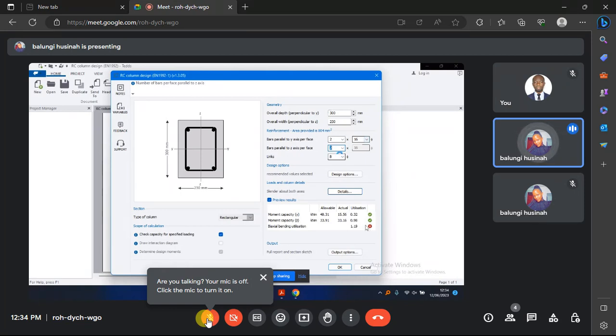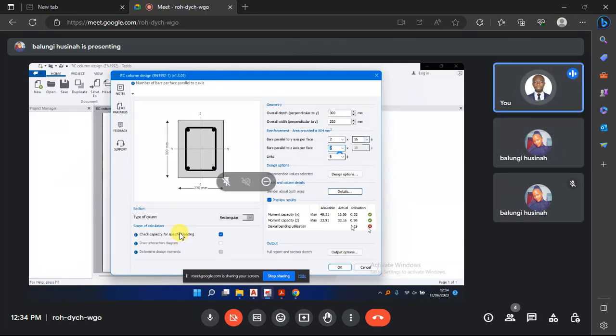The bending utilization is the one which is failing now. I think I've seen what I wanted. It's as if this thing just provides one bar size. There's no option for changing bar size in the same section. Okay. So let's put back the 3 and we have our 16 bars, which has no problem.